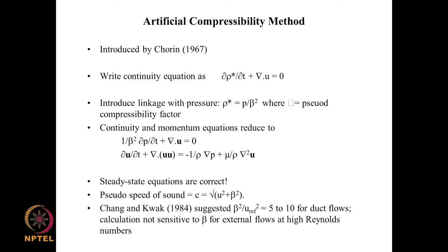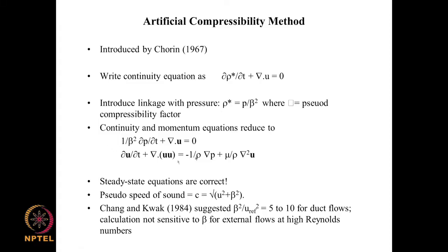So under steady state conditions, these equations can be considered to be accurate. So this provides us a means of getting a steady state solution even for incompressible flow, using compressible flow methods, through the use of this artificial compressibility here. So, we solve these equations with appropriate initial conditions and boundary conditions, and then march forward in time, and if we hold the boundary conditions steady, unchanging with respect to time, eventually under most cases we expect to reach a steady condition.